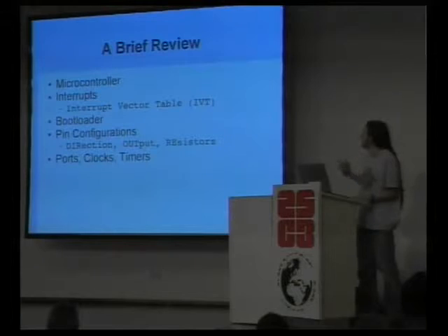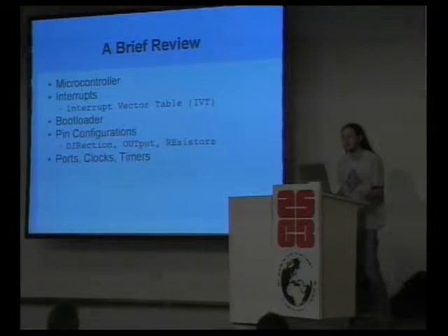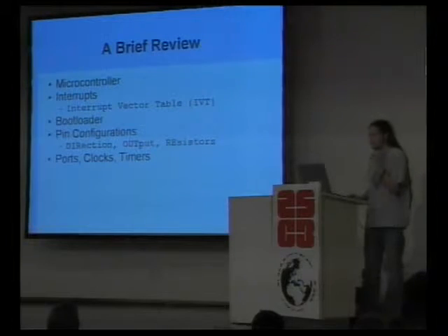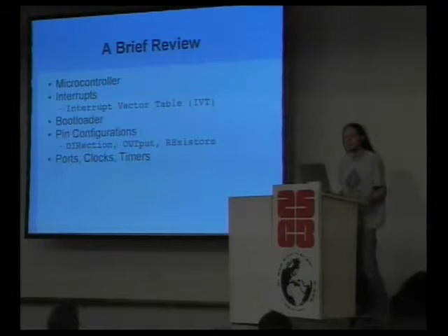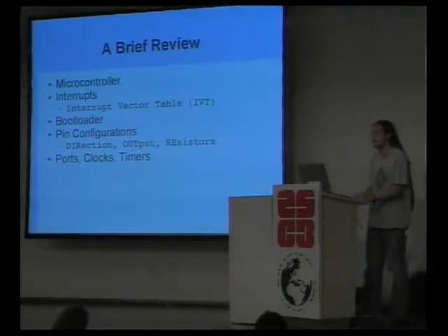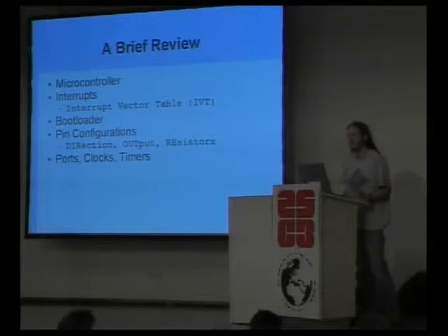I did a hack of the bootloader of this chip, allowing its password protection to be bypassed. And in this case, they actually wrote their own bootloader on top of that. So in addition to the bootloader that's in permanent master ROM, there's also one in flash memory. So when I say bootloader in this lecture, I'm not referring to the same thing as I did in my day one lecture.